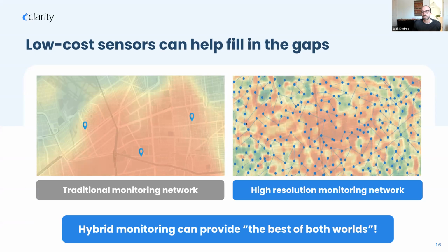So this is really where we see the most benefit of low-cost sensors, not in replacing regulatory instruments, but supplementing them to improve the spatial distribution of our understanding of pollutants. So while traditional monitoring can only have a few sites and give you broad swaths of air pollution spatial distribution, a dense network can offer more fine scale and better understanding of the air pollution in local communities and neighborhoods. Again, it's not about replacing reference instruments, it's about supplementing the information we can gain from these networks.